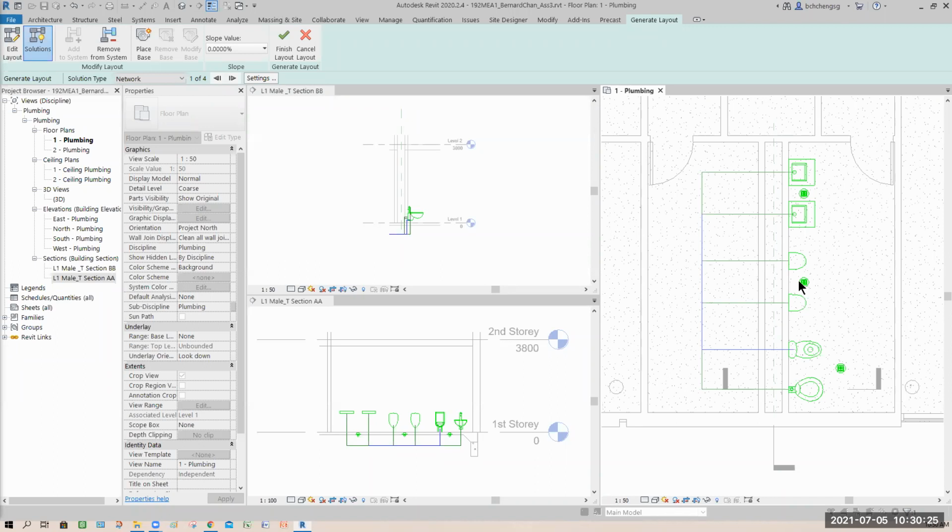It goes into the other toilet already, so people walk there. Initially, you notice if we never set the depth to minus 550, you'll see that it's on the surface. That means the students in the ladies' toilet will trip and fall. So just now you noticed that I changed this to 550. Now it goes underground. But of course, it should not be here. This main pipe should be in the center.